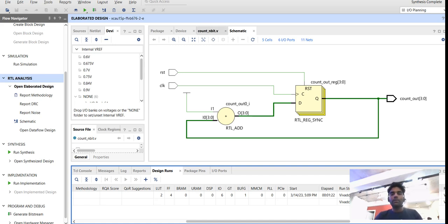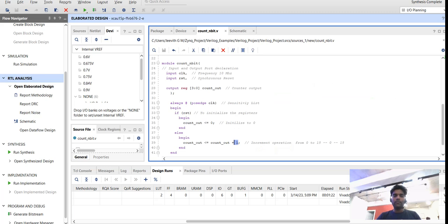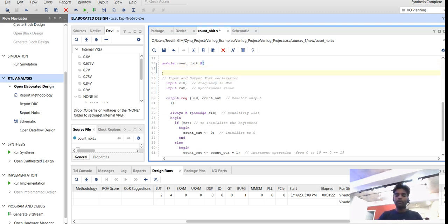Okay, so now I just designed this for a 4-bit counter. You can make it generic using the parameter option in Verilog. You can define one parameter mentioning the count width. When I say n-bit counter, you can define any count width and change it whenever you require. If you mention that parameter, the value changes you make in the top level will get reflected here as well.